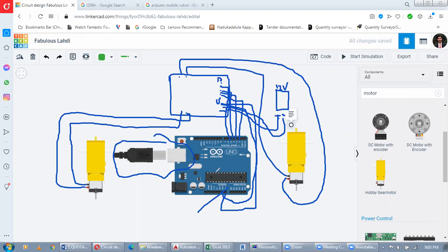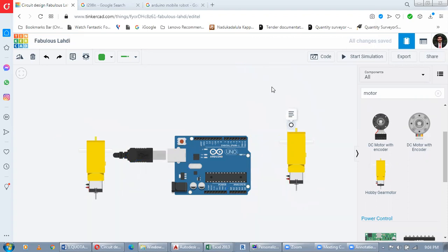The Arduino will be damaged, defective. Then afterwards you can't use your Arduino, right? So if you are connecting the USB cable to your computer, you have to disconnect the power and then you can code it. After you code it, you will disconnect this one and then you can power up. This is the way, right?